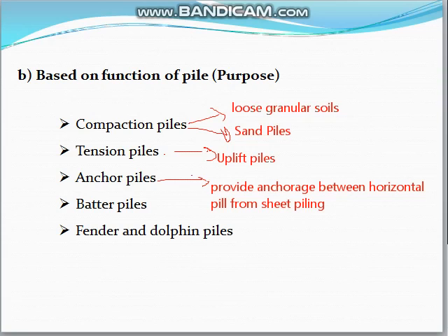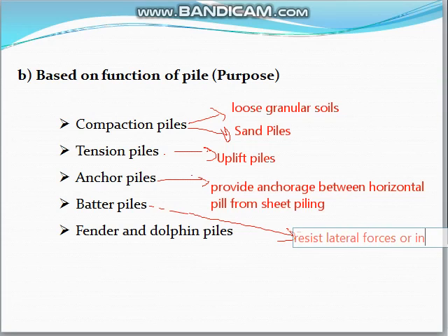Okay. Next, the fourth one is the batter piles. Batter piles are provided at an inclination to resist lateral forces or inclined forces.